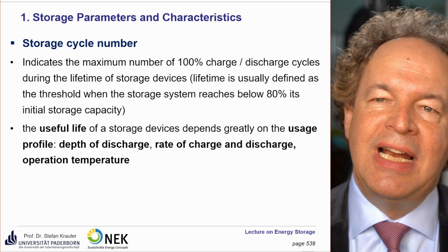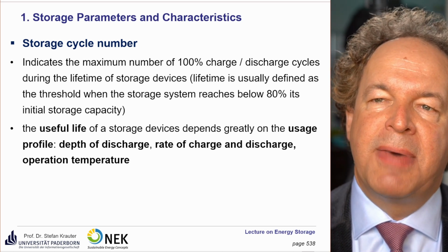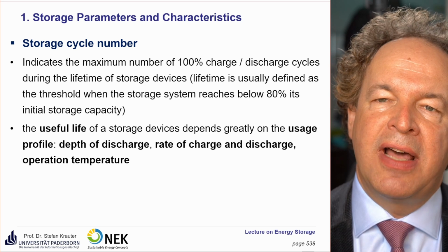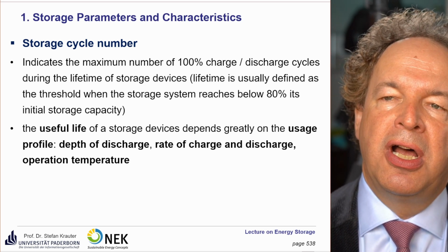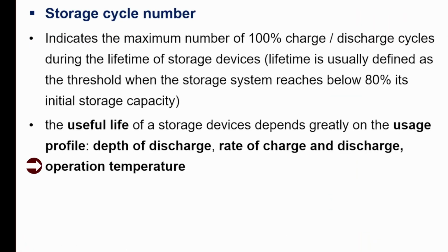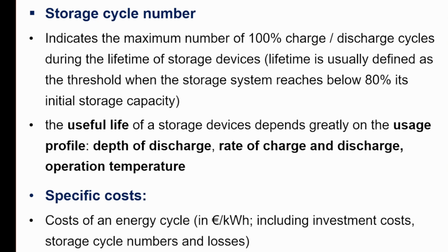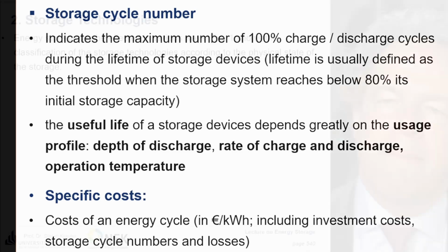The useful life of a storage device depends greatly on the usage profile, the depth of discharge, the rate of charge and discharge, and, very important, operation temperature. Then we have the specific costs, the costs of each energy cycle expressed in euro per kilowatt hour or euro per megawatt hour, including the investment costs, storage cycle numbers and losses.